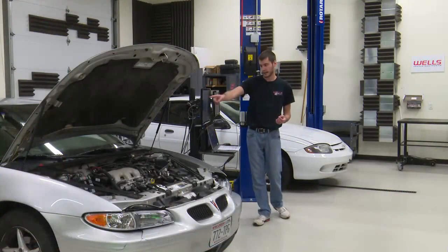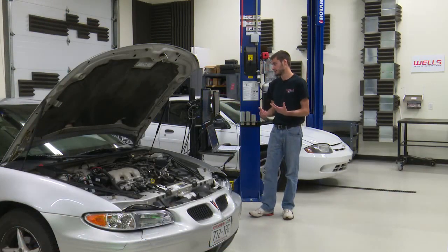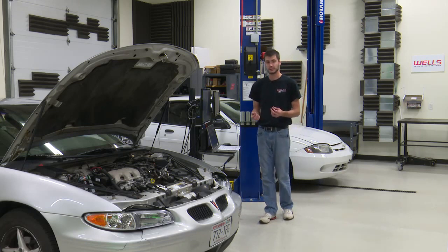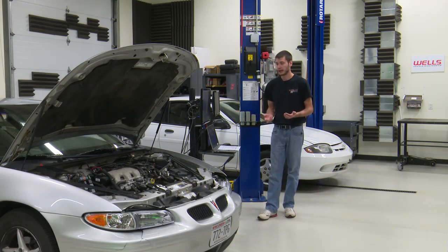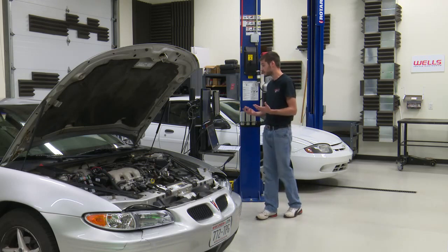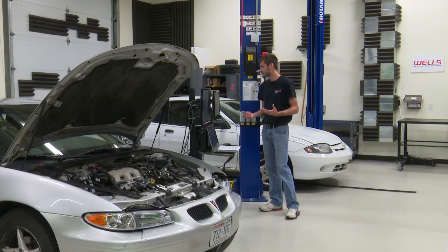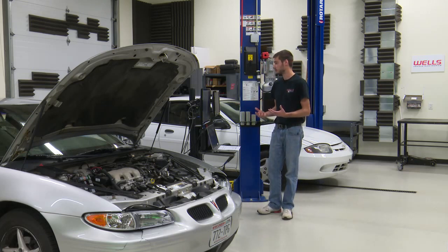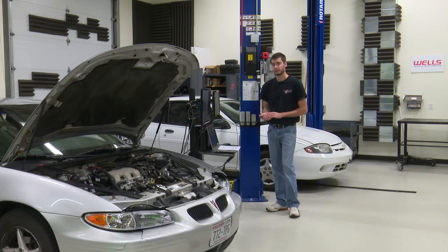Right now we're at atmospheric pressure because there's no vacuum being created by the engine. If Fritz goes ahead and cranks this engine over, the engine's going to start to make vacuum. If it starts up and runs, it'll create idle vacuum. If we're just cranking, though, it should create some amount of vacuum, and that right there is going to tell us that we have compression in the motor. That's correct, but it's not really a compression test, I wouldn't call it. But at least you're able to verify that the engine is capable of creating compression, capable of creating vacuum in the intake, and the map sensor is able to read it.